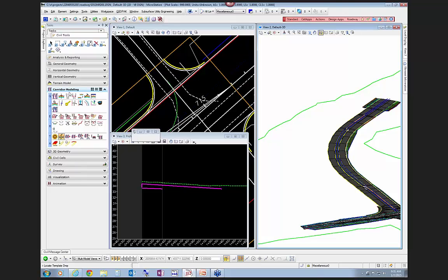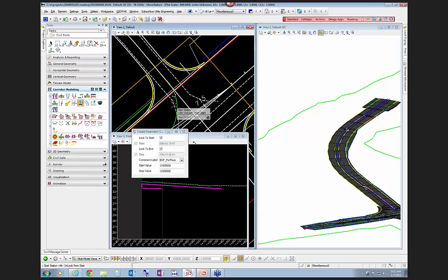So I would come over to the parametric constraints, and I may have this backwards, but I'm just going to Alt to lock to the beginning and Alt to lock to the end. And then I'm going to look for the switch value here, and I could pick it from this list, which should be now the left switch. And right now it's set to 1.5. If I set it to 5, and 5, it should turn that curb and sidewalk back on.